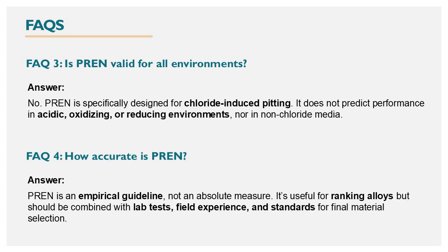Question number 3. Is PREN valid for all environments? The answer is, no. PREN is specifically designed for chloride-induced pitting. It does not predict performance in acidic, oxidizing, or reducing environments, nor in non-chloride media.